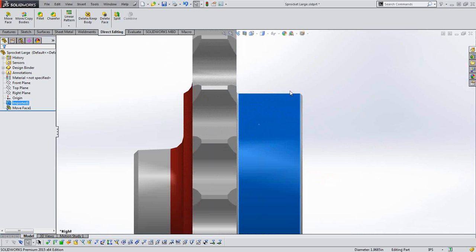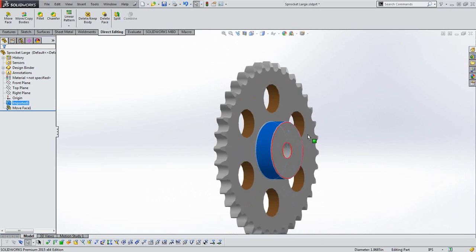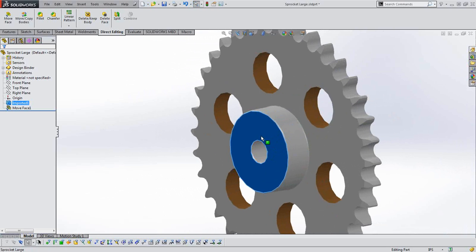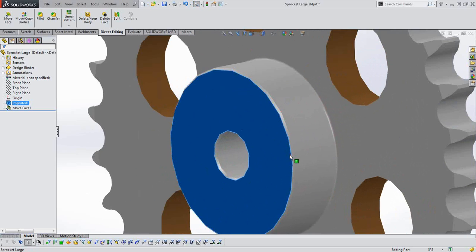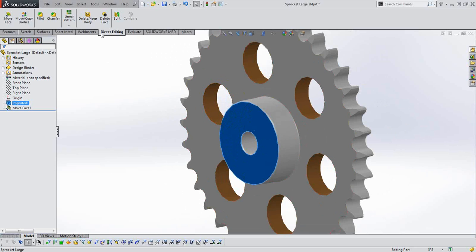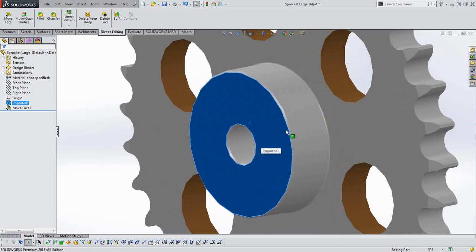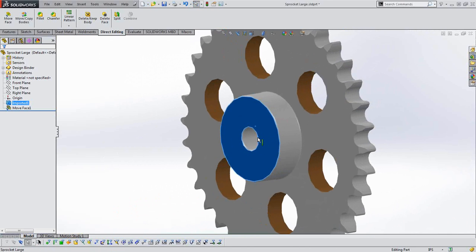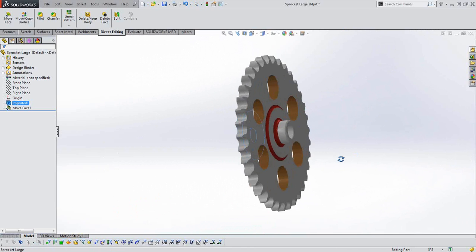And you can just barely make out there's a bit of a draft on this part. So with this face, if we try to move it, it actually is going to shrink that face for us, which may not necessarily be ideal. So there are times where you may still need to delete a face and start it over just to be able to edit things properly.